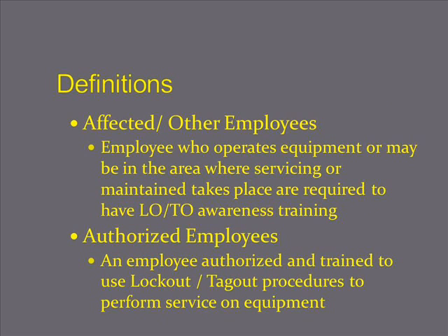Lockout-tagout definitions. The affected or other employees. These are employees who operate equipment or may be in the area where servicing or maintenance takes place. They're required to have lockout-tagout awareness training. Then there's you, the authorized employee. You guys are employees who are authorized and trained to use lockout-tagout procedures to perform servicing on equipment or electrical circuits.